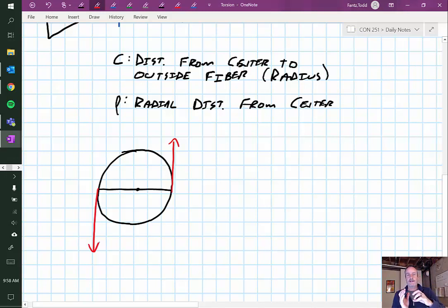And because they're going parallel to the section, meaning the section is like if I just lopped it off, they are considered a shear stress. So as I move from one side to the other, it is actually linear, meaning my shear stress is decreasing as I get closer and closer to the center, and it flips directions, and then it goes all the way out to the other side, right? And I end up with something like this.